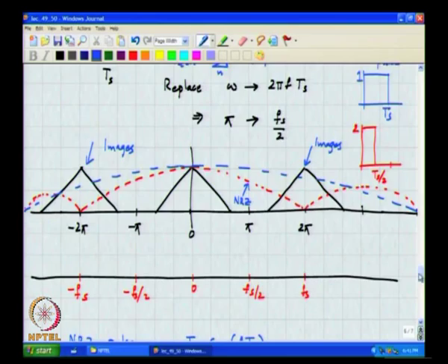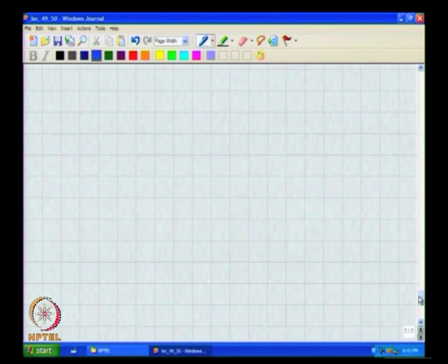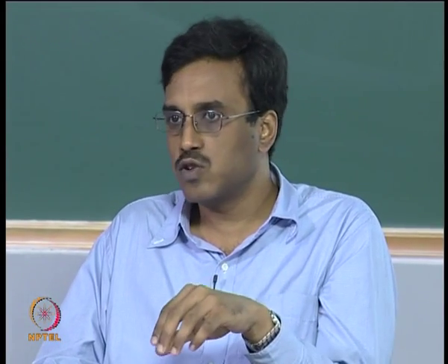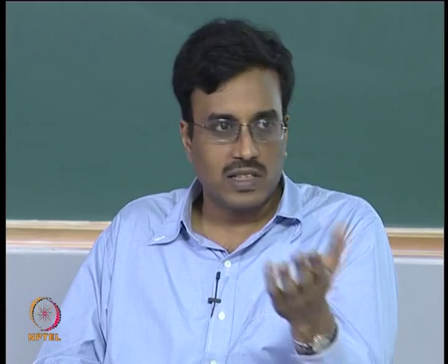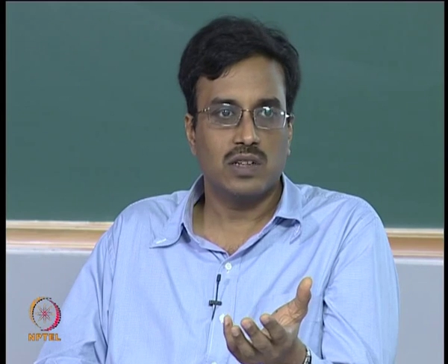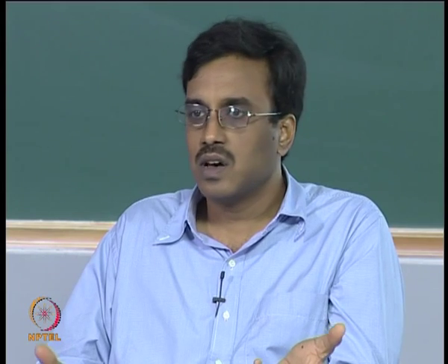So, now the question is, why would anybody choose a return to 0 DAC pulse, given that the signal has a lot more high frequency content. Do you understand? When you use an NRZ DAC pulse shape, the images are attenuated to a larger degree. The height of the pulse is smaller, and there are no transitions in the middle. So, one obvious question that could be asked is, if everything is so nice about the NRZ pulse, why even talk about an RZ DAC?